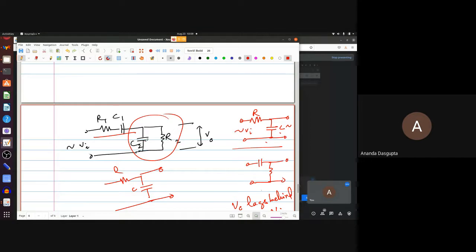So the important thing here for this particular circuit is, as you change your frequency from low to high, your output, which was leading for low frequencies, will lag for high frequencies. Somewhere in between, there will be exactly one frequency at which there will be neither lead nor lag.